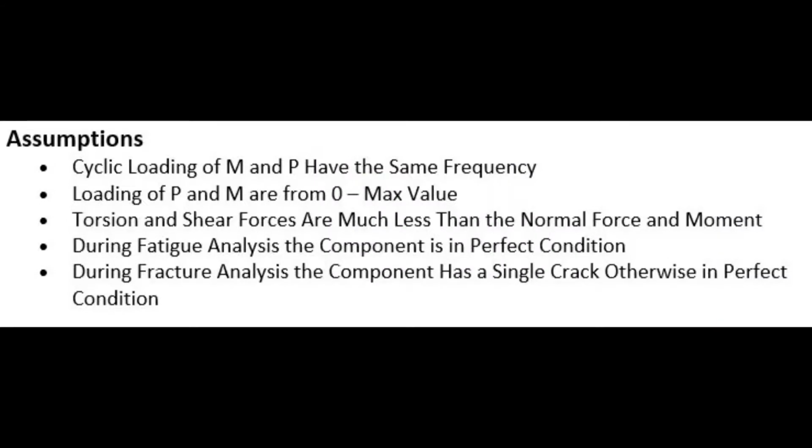Because the tip of the ski pole is almost always in snow, it was safely assumed for this analysis that it could not support a torsional force. Additionally, while it is possible for transverse shear force to be present from skiing, it was assumed that for most cases the shear force would be insignificant compared to the other forces present, thus it was neglected. This is justifiable because it is most effective to apply a force axially on a ski pole while skiing. Therefore, with good form, any transverse shear should be negligible.